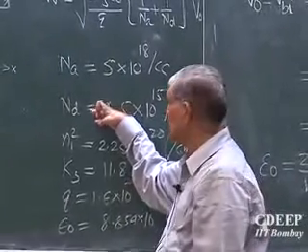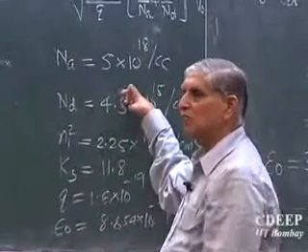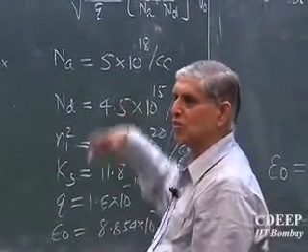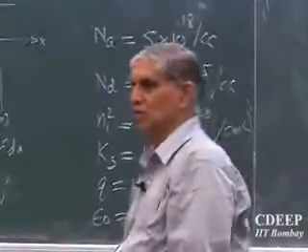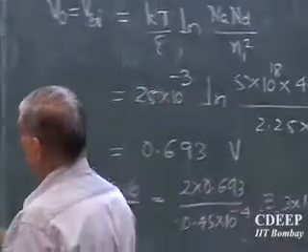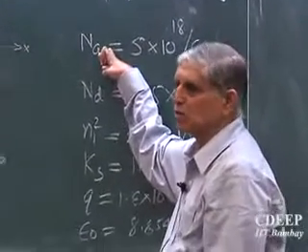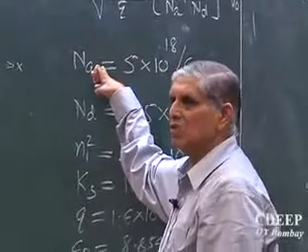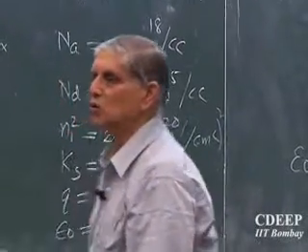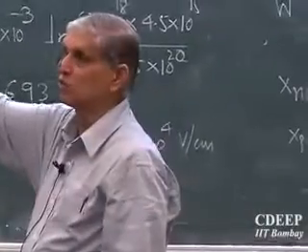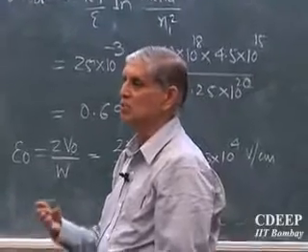So what we normally do is assume the NA and ND ratio for calculation, and then decide one value, okay, we'll use this as 10 to the power 16 or 15, and calculate the other one by knowing the ratio. Typically one doping is always higher, so we assume NA is higher. If we put 10 to the power 19, you can assume that, and then evaluate what the N doping should be to make the device characteristic which you started with. You say, okay, I want this. That's called design. This is what device simulators do.